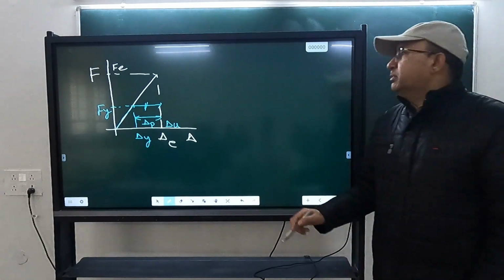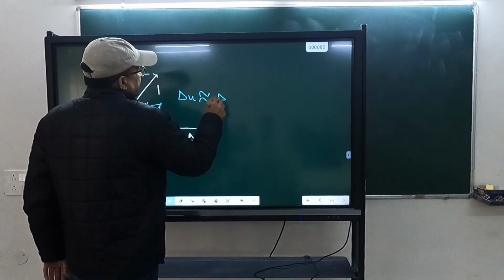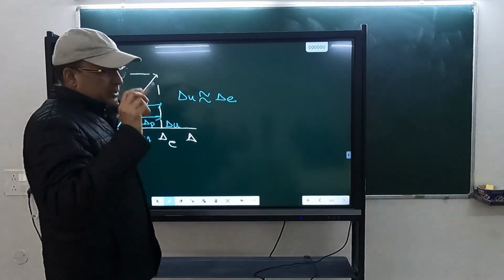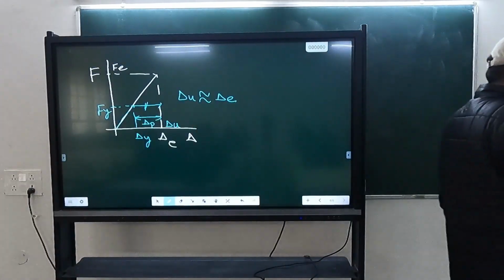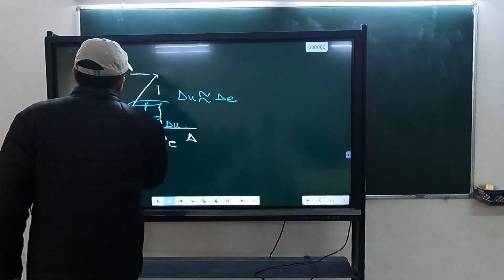So the equal displacement principle, you know that delta u is delta E: the maximum displacement of the elastic and inelastic structure is the same. If you design your structure not to yield, then whatever maximum displacement you get, if you design your structure, which usually we do, to yield during earthquake, then also its maximum displacement will be the same. Okay, and this is the damage.